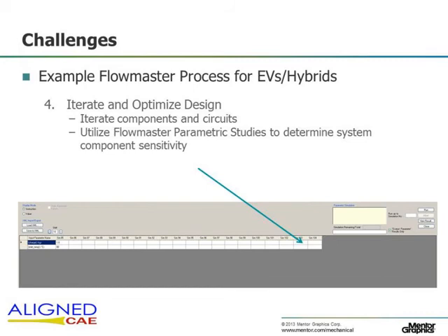So what we're doing here is iterating refrigerant charge in the system and evaluating compressor head pressure, evaporator discharge pressure, and condenser subcools over that cycle, just like one would run in a climatic wind tunnel when they're doing a charge determination. Because at some point you need to fix a charge in the system.